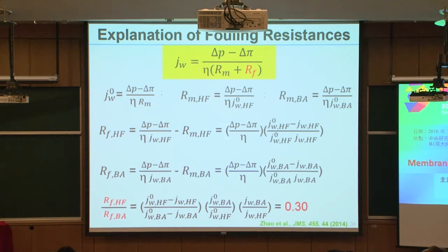When you have a foulant deposit on the surface of the membrane, that forms a new layer of membrane on top of the whole membrane, and that also provides resistance. All right. So if there's no foulant, like we put a 0 here, then suddenly this term is gone, right? We just use synthetic water, sodium chloride water without any foulant in there. So this term is gone, right?